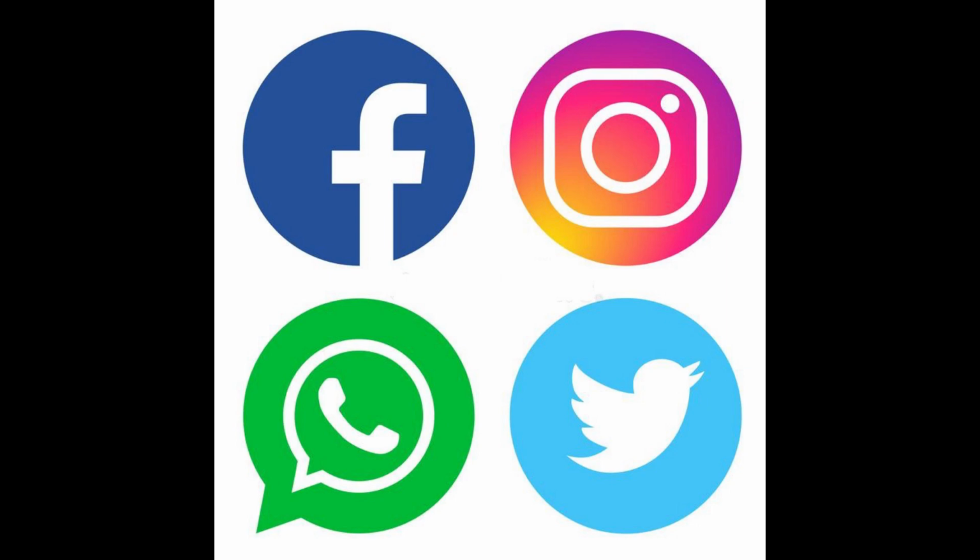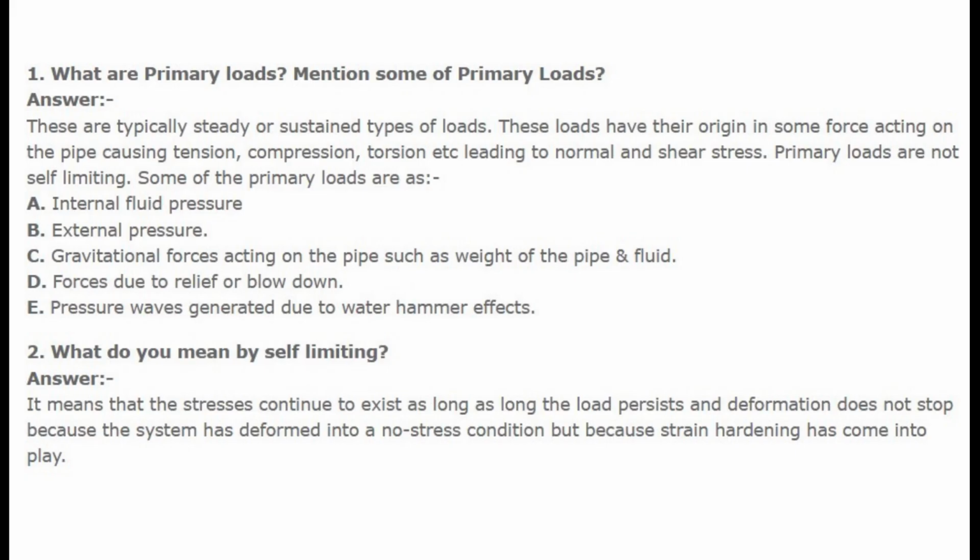Now, let's start the video. Number 1. What are primary loads? Mention some of the primary loads. Answer. These are typically steady or sustained types of loads. These loads have their origin in some force acting on the pipe, causing tension, compression, torsion, etc., leading to normal and shear stress. Primary loads are not self-limiting.